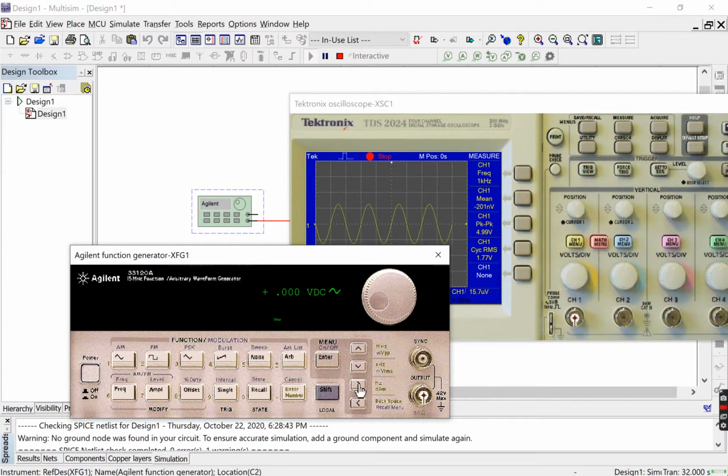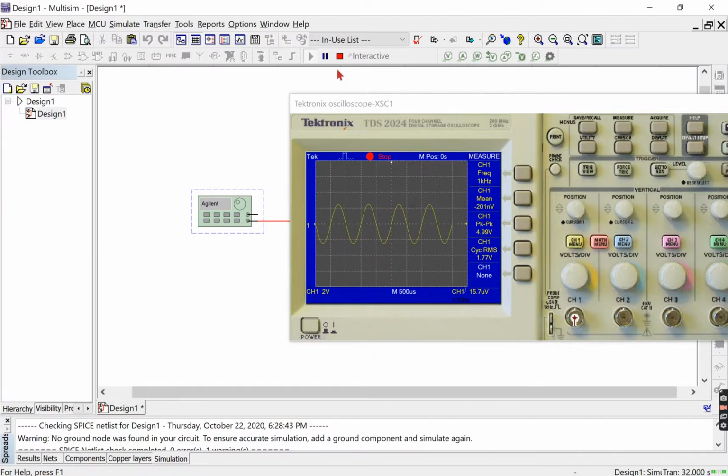So next I'm going to press on this arrow to move to the, I was controlling the integer. Now I'm going to control this digit right here to set it to 5 actually, so it will be 1.5 volts DC offset. Okay, now I'm going to close this window and then run the simulation again.